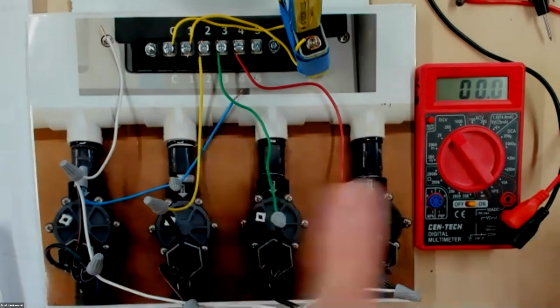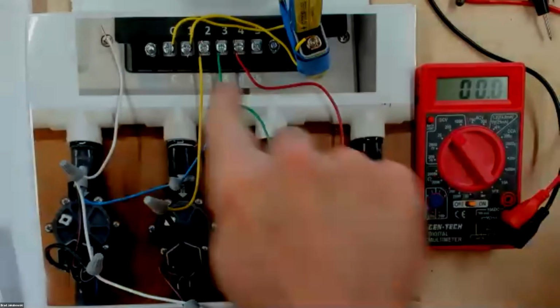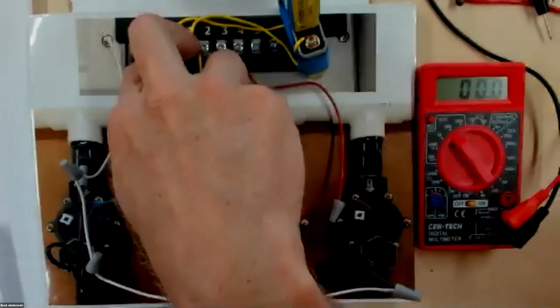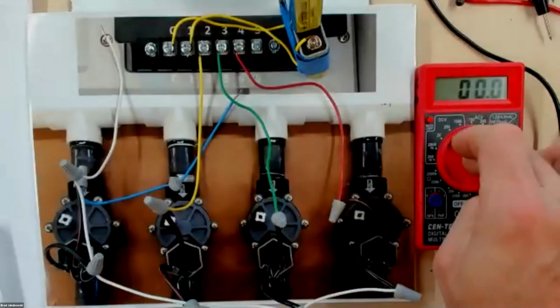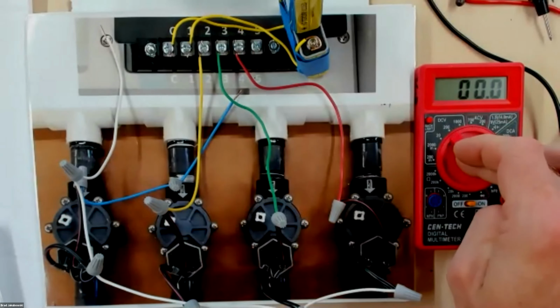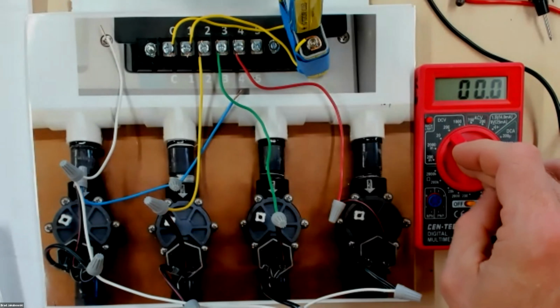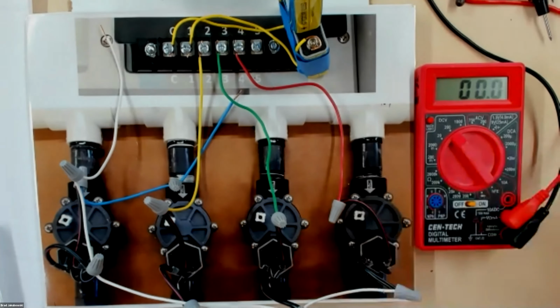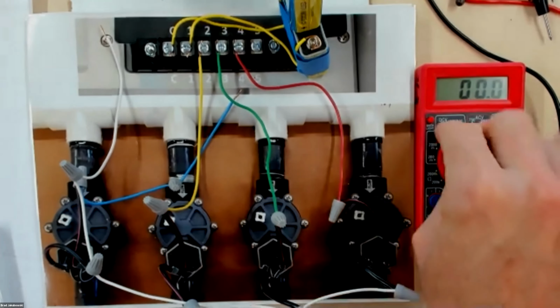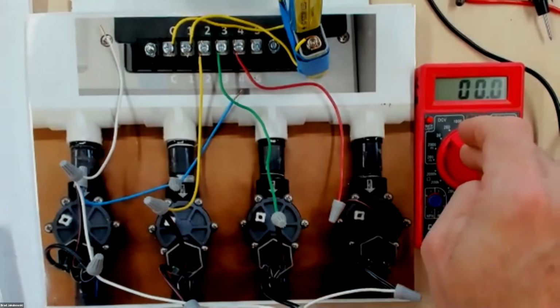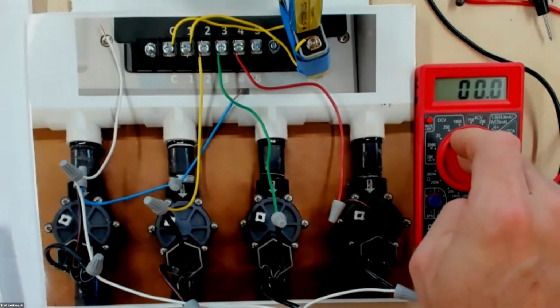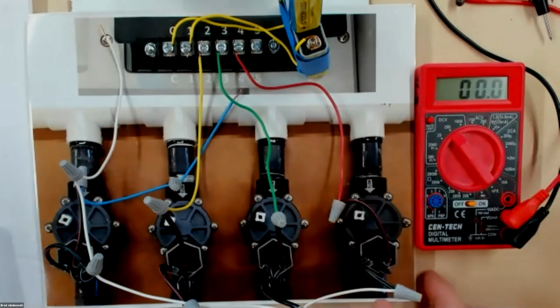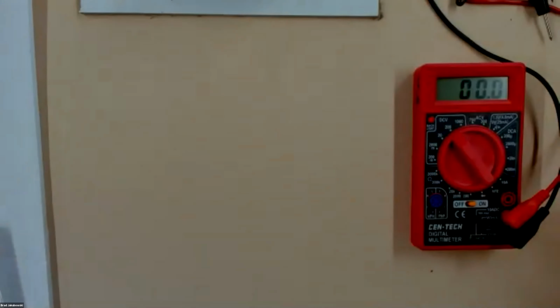Okay, so remember, if you're checking electrical voltage on a controller, make sure you have your meter set correctly, because otherwise you'll get some erroneous readings and you could actually burn up your multimeter when you're checking voltages. When you're checking resistance, make sure that the power of the controller is off. That's the key. Sorry, I didn't mean to confuse you there. All right, so that's a little bit about that one.